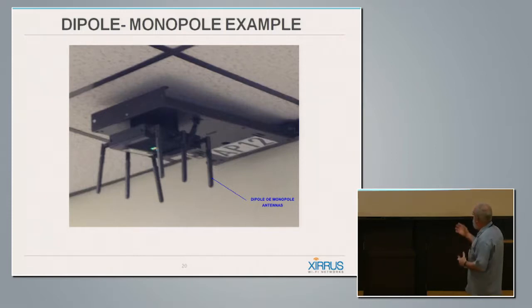It's not up to you, but whoever decides to use certain antennas from a certain source, it's better to be careful enough to know that the design is done properly. Sometimes it's better to put ferrite on the coaxial cable, which acts as a choke to minimize radiation from the cable, to make the coverage more consistent and less sensitive to the orientation of the antennas.